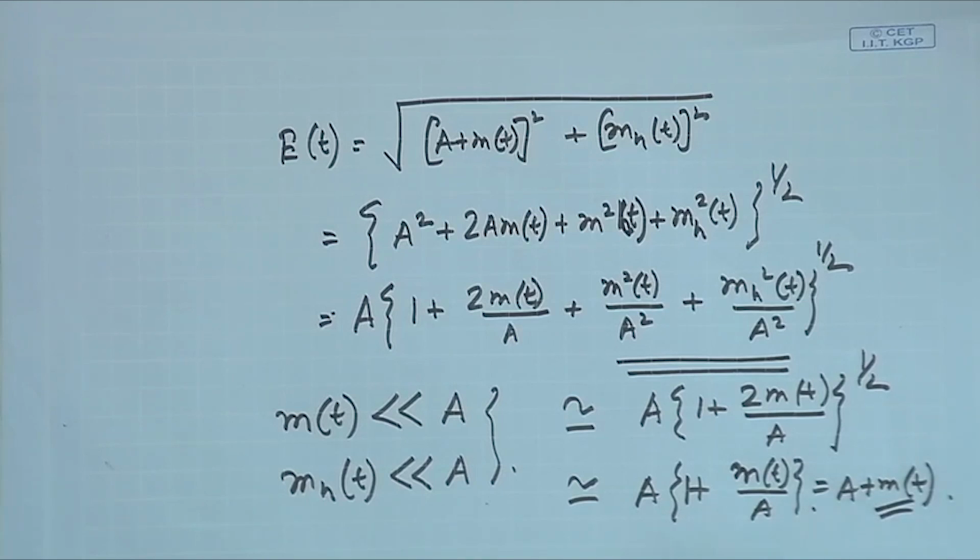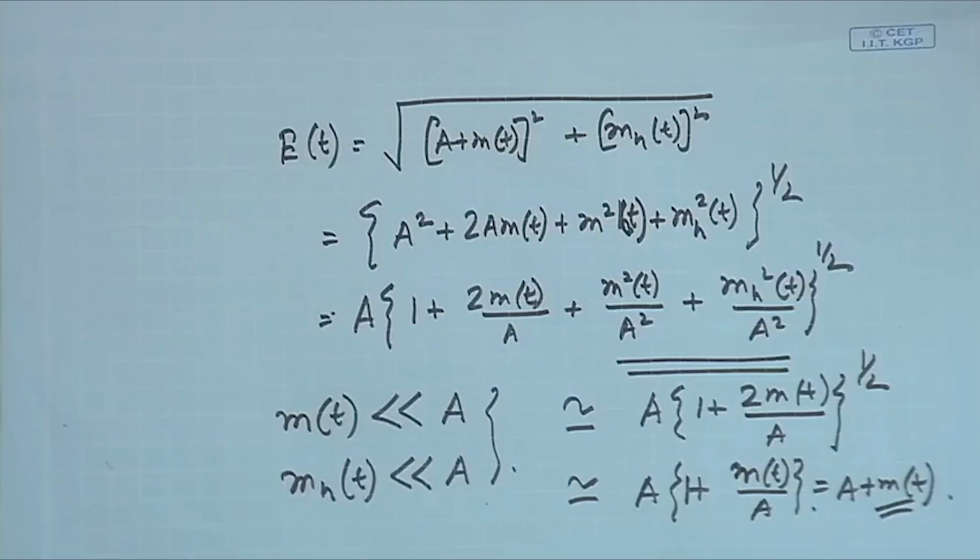So, the condition is in SSB also like AM. See, DSB had a version AM where I was adding carrier, right, and with carrier I was able to do my receiving in a very simple way. So, I was able to do that. What I was doing, I was just putting envelope detector followed by a DC blocker. Same thing I can do over here, but there is a condition.